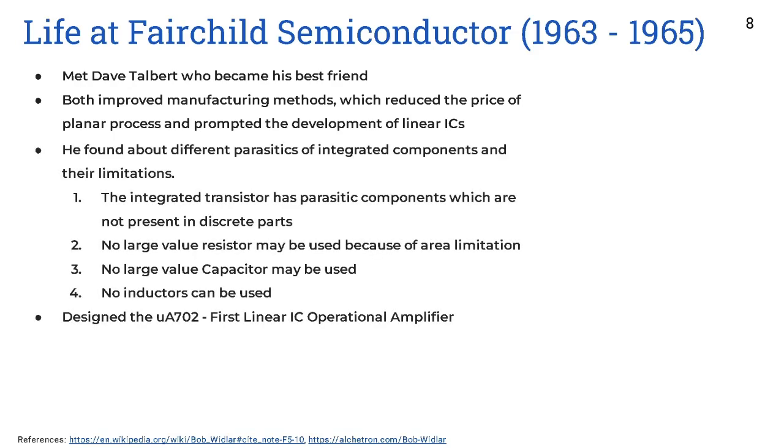While working at Fairchild Semiconductor, Widlar found different limitations of working with integrated components as compared to discrete components. These are some of the parasitics, as you can see here, these four points of integrated components. The first point is that the integrated transistor has parasitic components which are not present in the discrete parts. As soon as you put the transistor in the integrated circuit, it has some parasitic components which will disturb the functionality of the circuit.